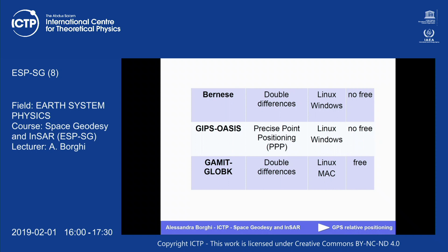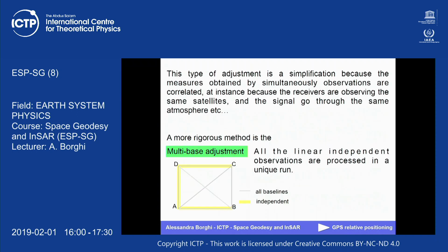Also the network problem with independent observations. But it is a problem that when you have a software, now this is important, I wanted to tell you this before, but I forgot it. Okay, scientific software know that they have to use independent double differences and independent baselines.